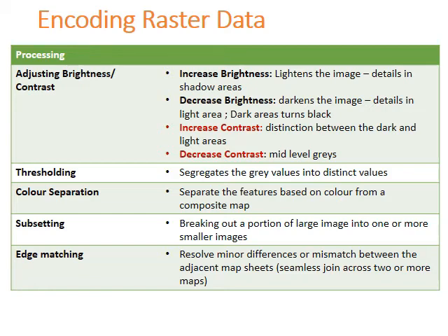For example, you take a satellite data which is going to have a very big area, and all that area is not used for your analysis. So your study area may be very small. Out of that entire image, you have to subset only your study area. For example, it may be a watershed boundary or an administrative boundary. So to do that, you have to do a process called subsetting, which will bring out your portion of your analysis separately, which becomes a smaller image, and further analysis can be done with that.